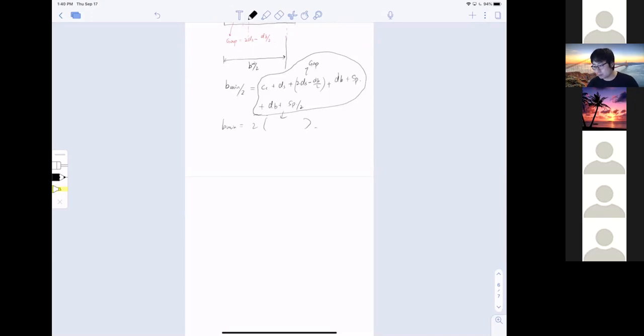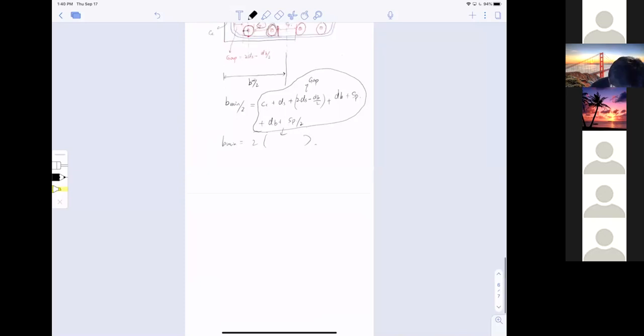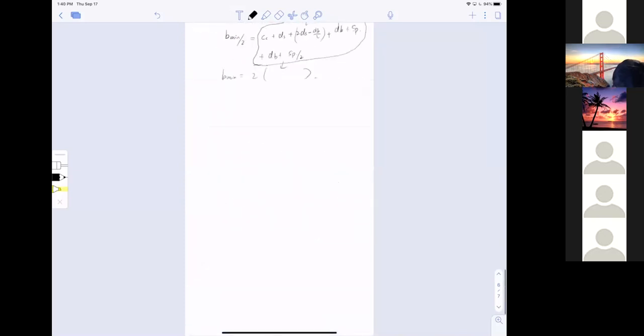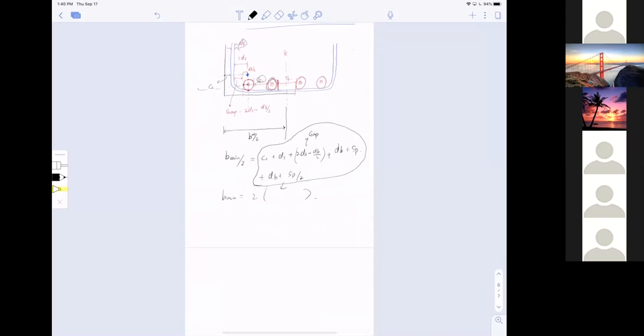Anything else? Yeah, one final question. Whenever we're finding effective depth, or not even effective depth, just the strain epsilon t, I guess it would be called, we always use the distance to the bottom row of the bars whenever there are multiple lines. Yes, always. That's called dt, by the way. If you have 2 rows, it's always dt. And we always use that dt to find phi, essentially, right? Yes, phi is always a function of dt.